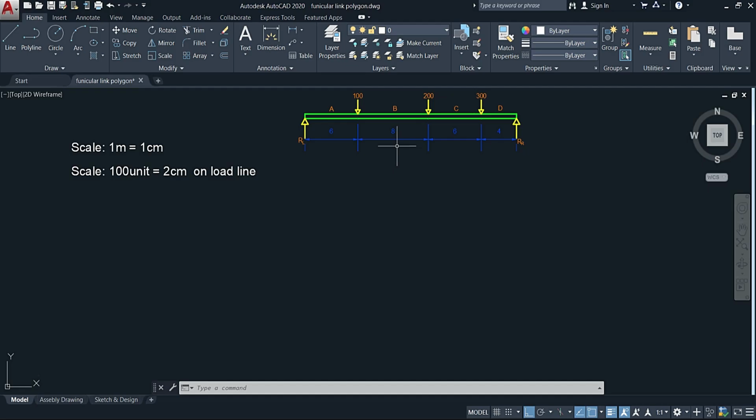So let's get further into things. Now, before we get started, it is very important that you understand that when you are producing these drawings, you're drawing based on a set scale. You'll determine this scale whenever you're doing yours. As you can see here to my left, I have a scale. I'm saying here on my scale, for every 1 meter in measurement, it is equal to 1 centimeter on my paper. In this case, it is in AutoCAD. When this is printed, it will be the same 1 centimeter.